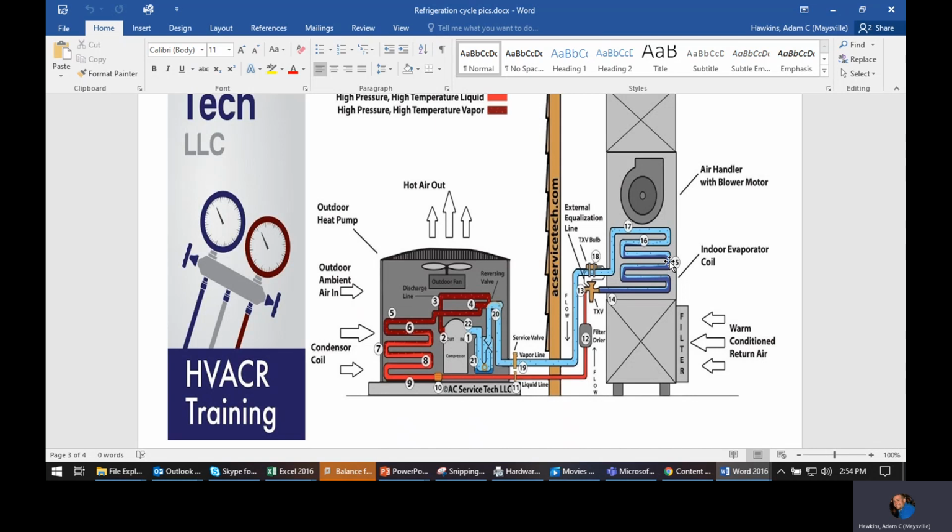So this is an easy misdiagnosis. And it's also a case where you would say the latent change matters as much or more than the coil being colder, because if you have a low charge situation, your airflow is going to be warmer than you want it to be. Your superheat's going to be warmer than you want it to be, but your pressures are going to be low. And so if you're just going by pressures and you say, well, if that's cold, then that's an indication of low charge, but at least it will cool really well.